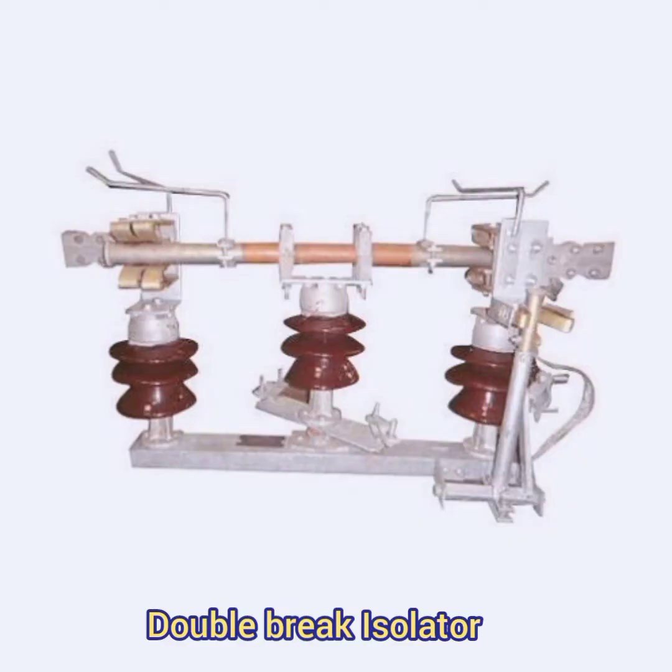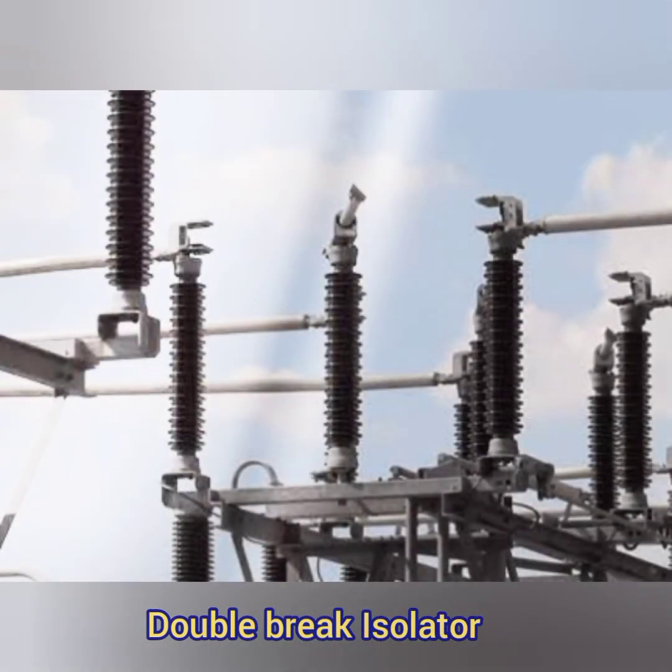The rotating shafts and the insulators are present in the downside, which means the insulator is the carrying portion of this double break system, which carries the male and female contacts, and the rotating shafts and the driving mechanisms are inside the post insulators.